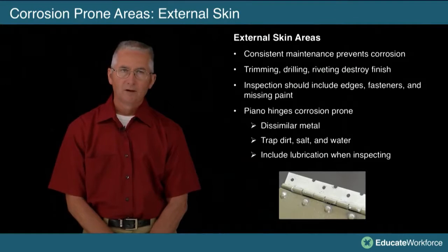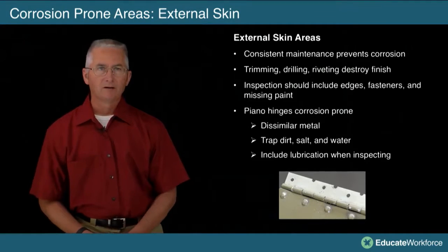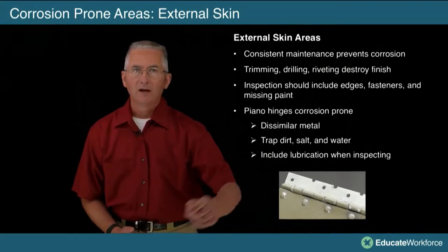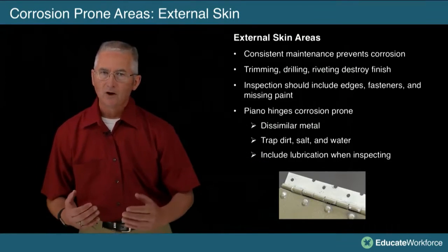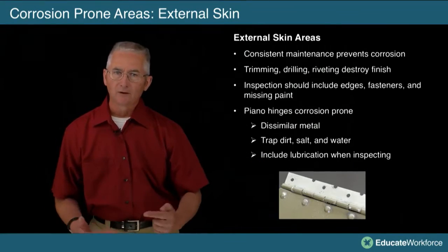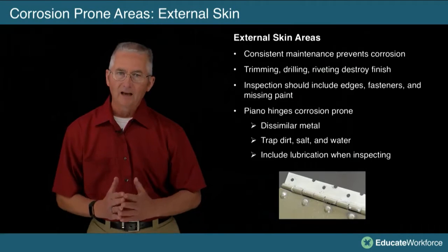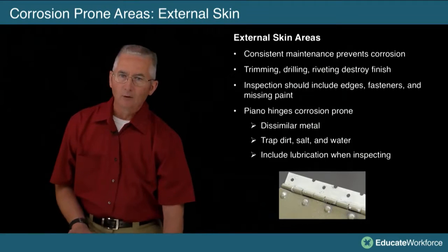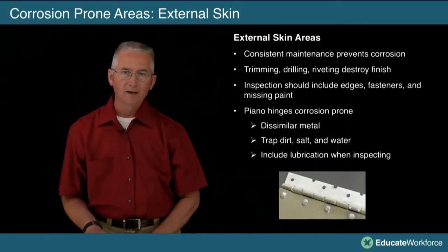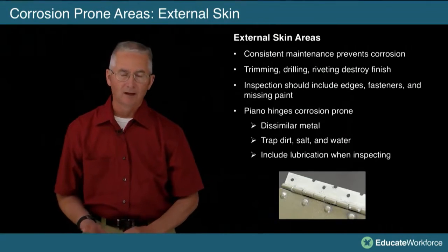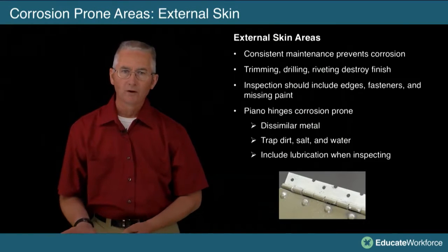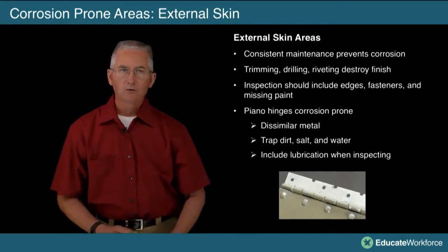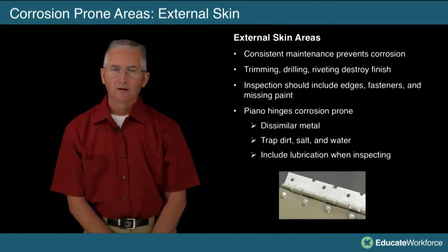Piano hinges. Piano hinges, like we see right here in the picture. If you notice on that piano hinge, you've got an aluminum hinge with a stainless steel pin, and every time that opens and closes, we have movement. And no matter what you do to that, you can't keep it painted, you can't keep it greased. Anytime you put any grease or oil or lubricant on there, that's going to attract more dirt. Just watch them. Piano hinges like to corrode.